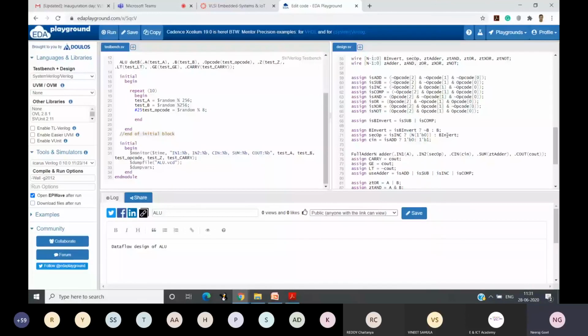Whenever we are doing assignment, it is the duty of the designer to match the number of bits from the left-hand side to the right-hand side. Otherwise, sometimes Verilog will not give an error, but your design will finally show an error which would be difficult to debug. Similarly, we also find Cin.